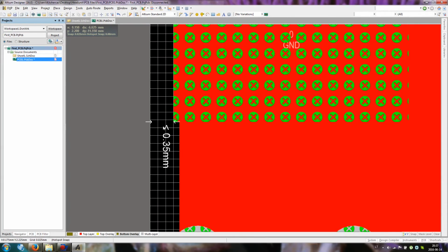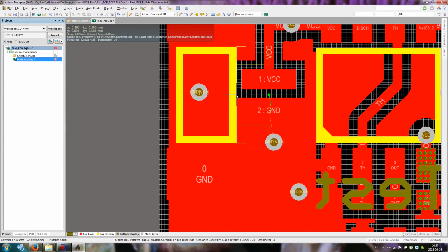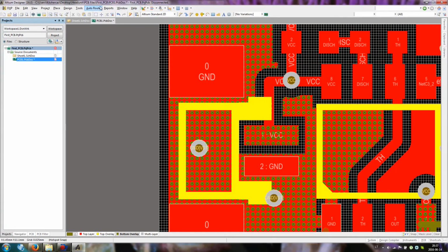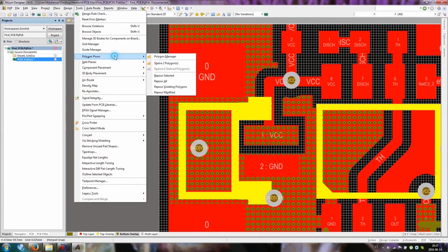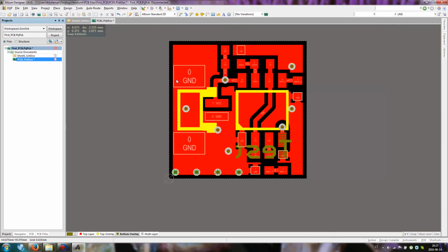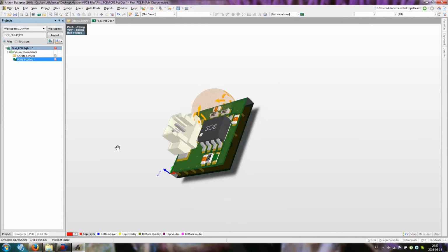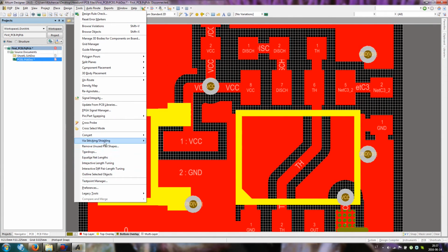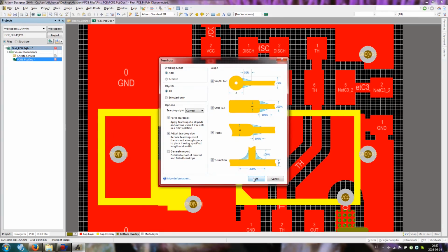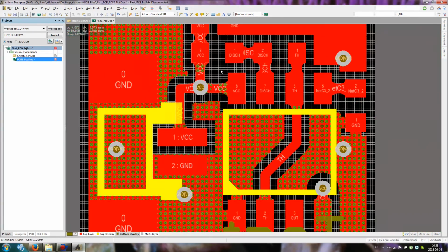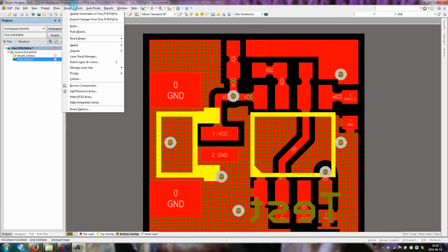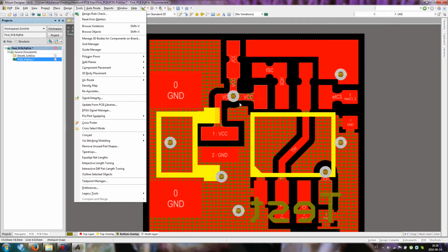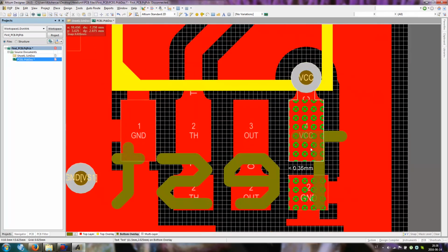And of course, it also says that it's again, and let's repour all. Okay, so as you can see, this is how I do it, and we can also add, just to make it a bit nicer, teardrops. Teardrops basically will make teardrops on each node. It will help with the copper manufacturing process. Again, because we created shapes, we need to again repour all, and that's it.